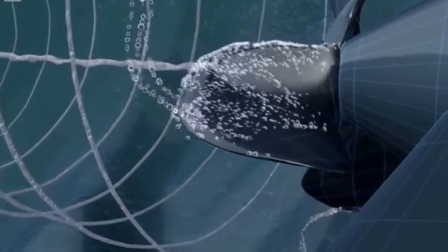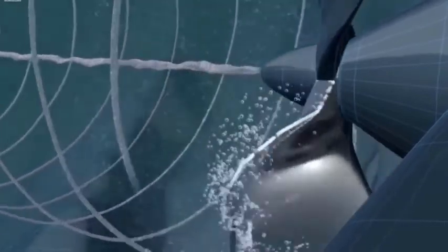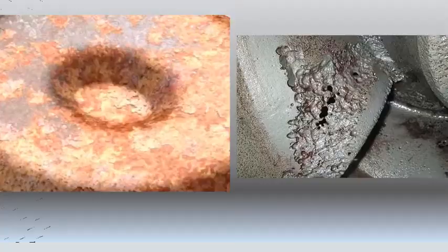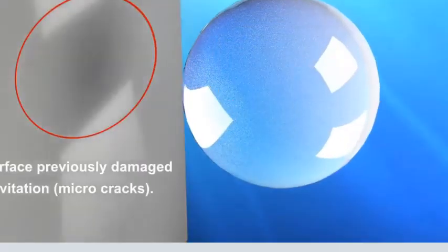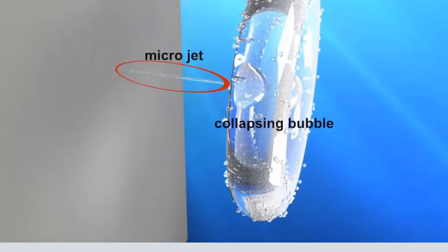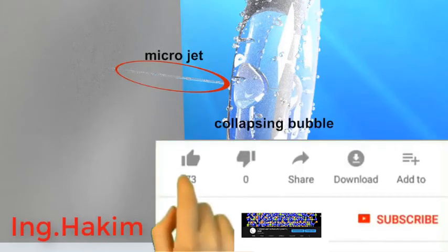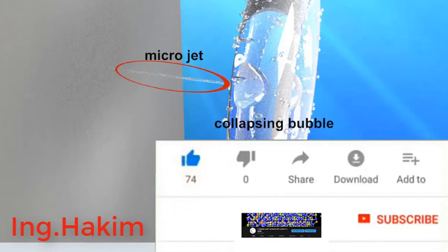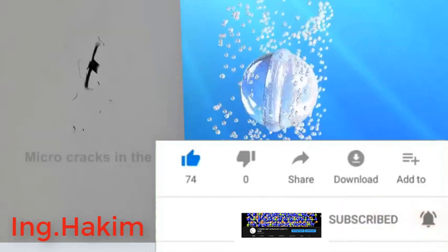Cavitation must be avoided, or at least minimized, in flow systems, since it reduces performance, generates annoying vibrations and noise, and causes damage to equipment. The pressure spikes resulting from the large number of bubbles collapsing near a solid surface over a long period of time may cause erosion, surface pitting, fatigue failure, and the eventual destruction of the components or machinery. The presence of cavitation in a flow system can be sensed by its characteristic tumbling sound.